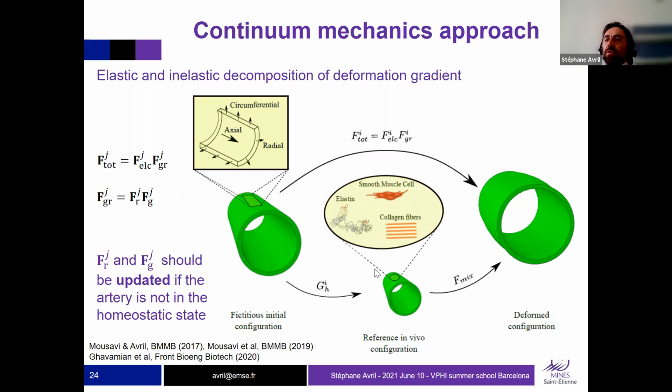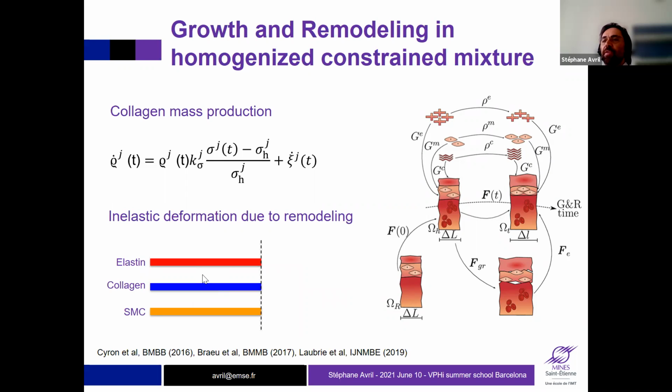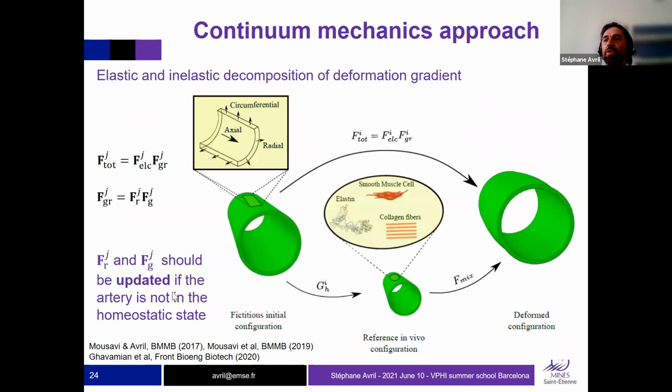So all the models, as I said, were developed quite a long time ago, and they were proposed by J. Humphrey, but we struggled a lot to implement them in a finite element framework for patient-specific aortas, because most of the time they had been used for cylinders, and patient-specific aorta brought some issues related to numerical stability. One of the main issues of these models is this pre-stretch that you have to apply everywhere, and that can create some instability issues that we had to overcome by playing around with different initial pre-stretch until finding a good combination of them for the different constituents. That's explained in our papers here, but that was the main innovation of our work in that field, because, as I said, the models were quite old before.